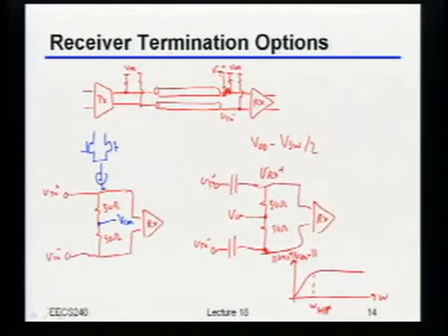You're transmitting a square pulse. Okay, you're transmitting a square pulse. What does that mean? Because it's infinite bandwidth. There we go. So in particular, what happens if I was trying to always transmit zeros? So I just tried to transmit 0 forever. Oh yeah, never make it. It's not going to make it through, right? Eventually, this thing is just going to leak away, meaning the voltages here are just going to leak away and go to 0, right? So if you do something like this, you have to be careful that your data is what's called DC balanced, meaning that it doesn't have any content at DC. Because if it does, that stuff's not going to make it through the AC coupling cap.